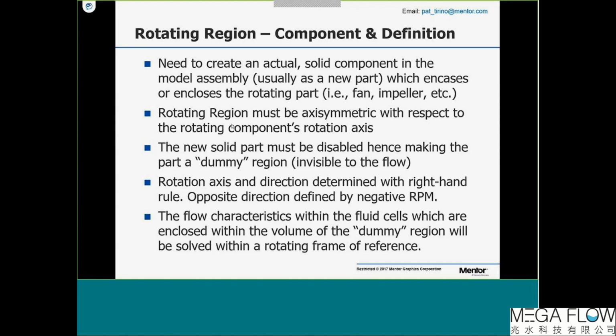And in component control, EFD allows the user to make a part invisible to the flow by disabling it. When we disable something in EFD, we can almost call that part a dummy part now. It's still a solid part in the CAD, but as far as EFD is concerned, it's invisible to the flow, so it has no effect on the flow.